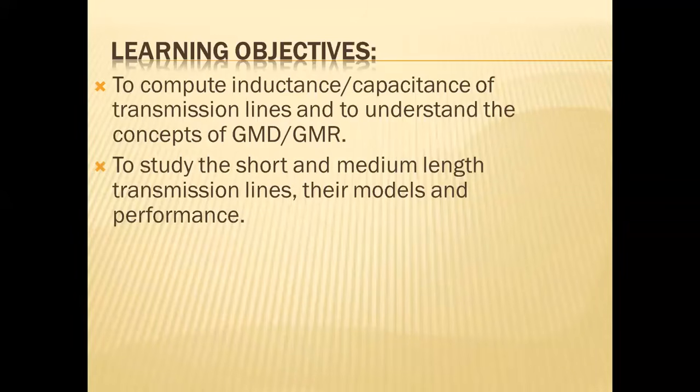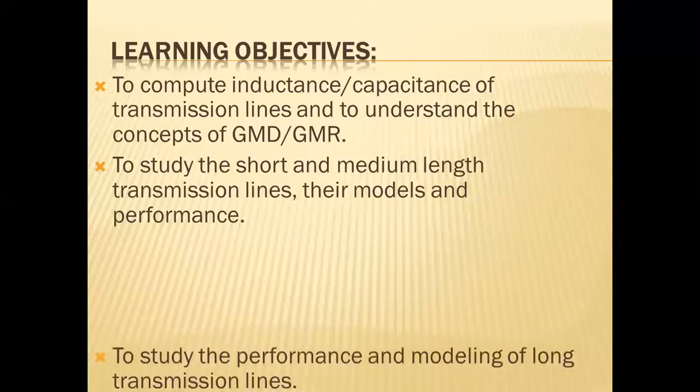For medium transmission lines, as you can remember from circuit theory, when you discuss Z parameters, Y parameters, H parameters, you'll be studying transmission parameters also, where you discuss A, B, C, D. So the transmission lines will also be modeled to obtain the values of parameters A, B, C, D. Using those parameters, we'll be estimating performance of the lines, meaning the efficiency and voltage regulation of the line.